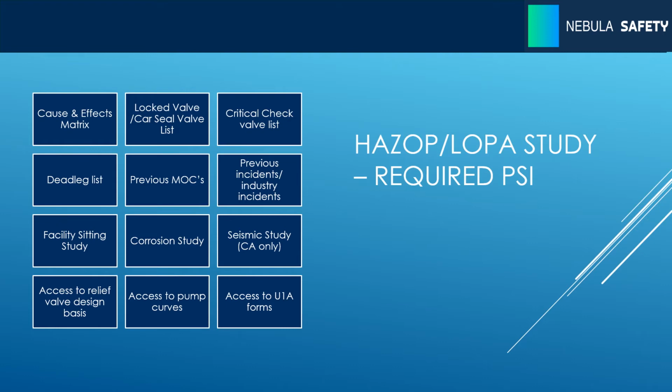Many hazards that have happened in industry are a result of changing it from the original engineered design. Typically, if you just leave it at design, never change it, well, you should just be able to run the process as it was meant to be run forever with no issues. But of course, things change, and those MOCs provide the PHA team a way to look at those small, minute changes on a holistic level, look at the entire process, and see if maybe something was missed in the hazard review that most likely went alongside that MOC.